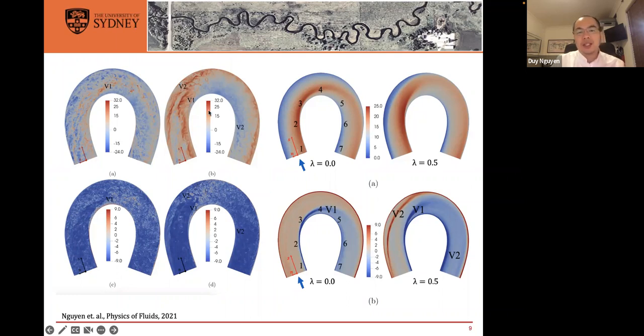But the difference is that in a neutral flow, because of more mixing, this high streamwise fluid does not slide quickly from the inner to the outer bank, but goes cleanly along the center line, and does not reach the outer bank wall until much further after the bend apex.